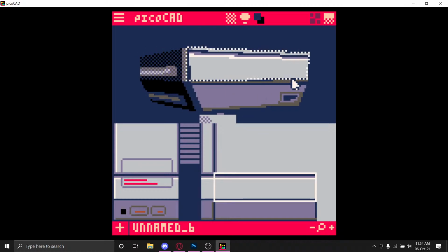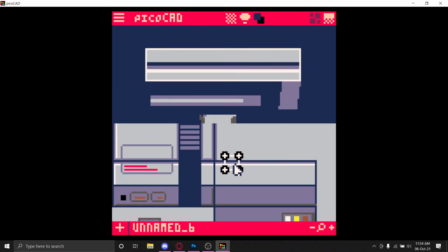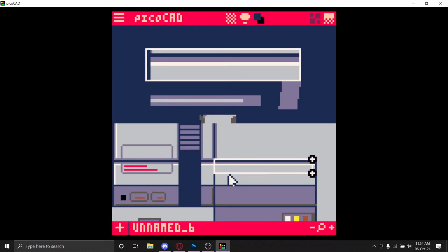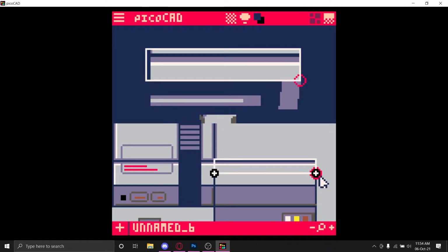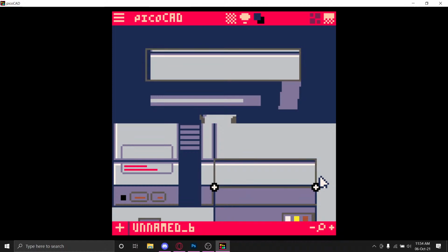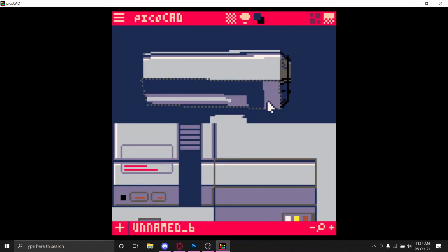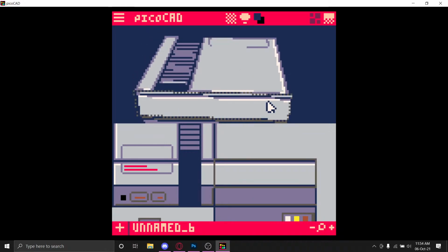Another face is made. Now this face is left. Again, just drag it down, hold X, select multiple, extend. So we can create. I just try to create a very simple design for you today, and I'll show you another complex design where you can edit, you can manipulate even bigger shapes. Right. This is one thing I in fact missed.